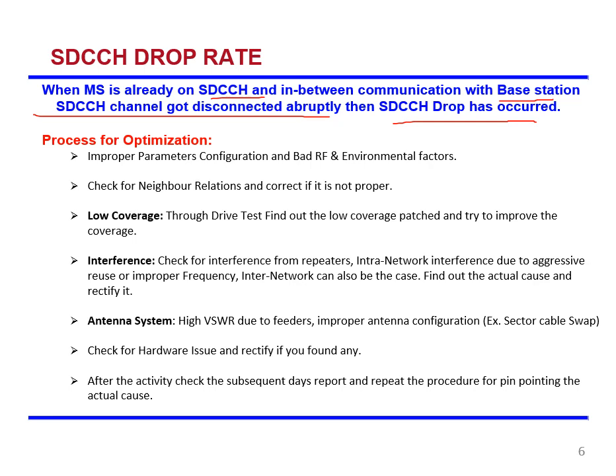And how to optimize, we have seen several steps are there for optimization. What are the several steps? If your SDCCH are dropping, what does it mean? Maybe coverage issues are there. Definitely one of the chances will be bad RF or environmental factors. Maybe some coverage is less.